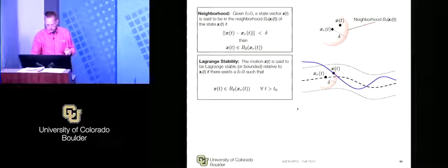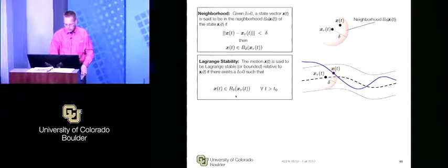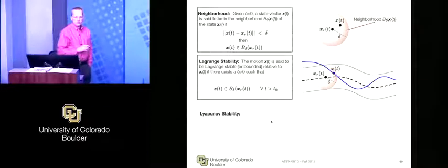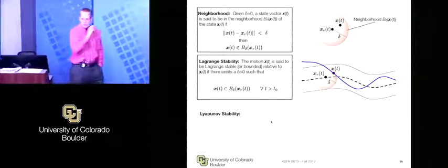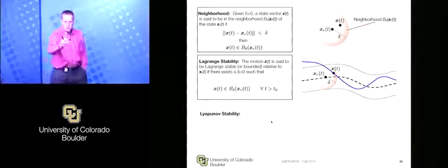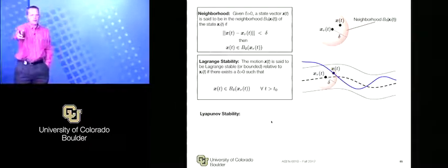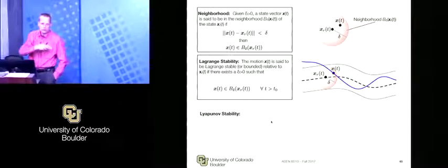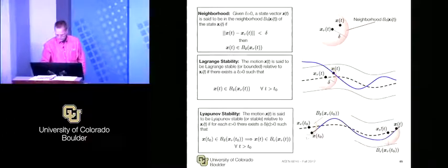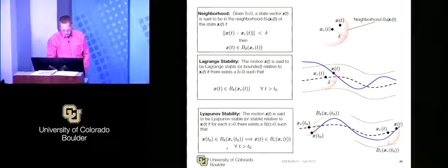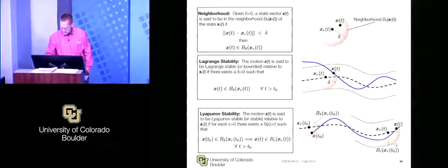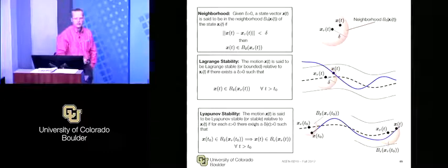That's what we're saying. So there's a ball, but this delta doesn't depend on initial conditions. Lyapunov stability, on the other hand, again, we have a final ball, a final area we're converging to, but here, Gabrielle, does that final ball size depend on initial conditions? Yeah, you start in one neighborhood and you... Yep. So this neighborhood now all of a sudden depends, this epsilon depends on the initial stuff. There's a coupling, a relationship between them.